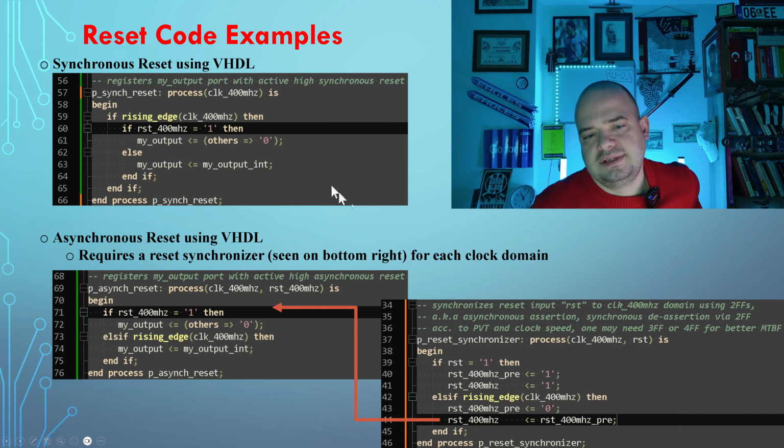So this is the difference, just the name of the timing parameter changes. If the input is synchronous like this, we call it setup and hold slack. If we are considering asynchronous inputs, then we say recovery and removal slack. Okay, this example is for the synchronous one.